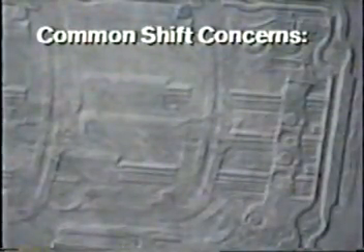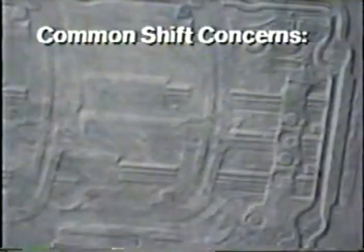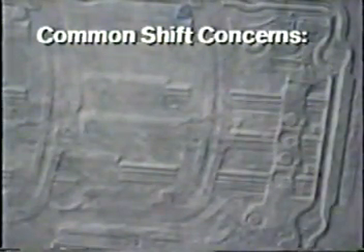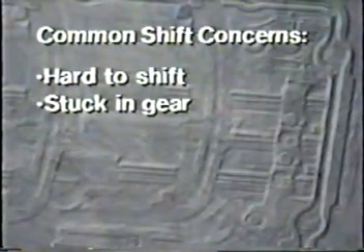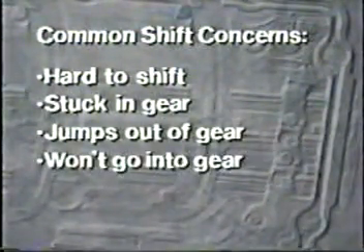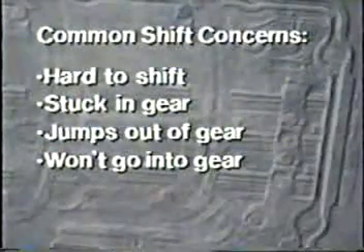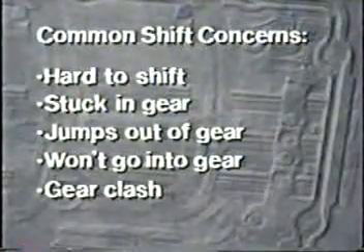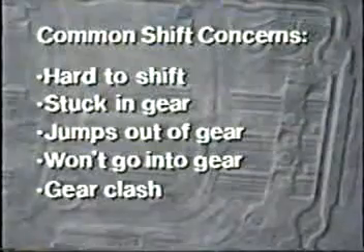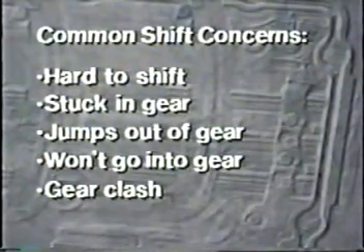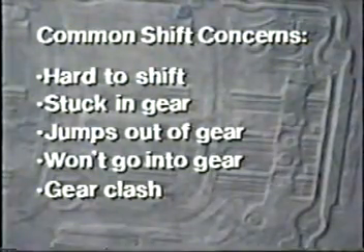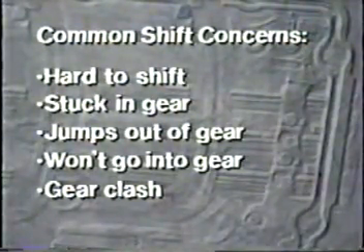The common shift concerns with manual transmissions, transaxles, and four-wheel drive transfer cases are hard to shift into gear, stuck in a gear, jumps out of gear, can't shift into a specific gear, or gear clash when shifting. Diagnosing and repairing these kinds of shift problems goes much faster when you have a keen understanding of how all the components related to shifting work and the symptoms created when they fail.